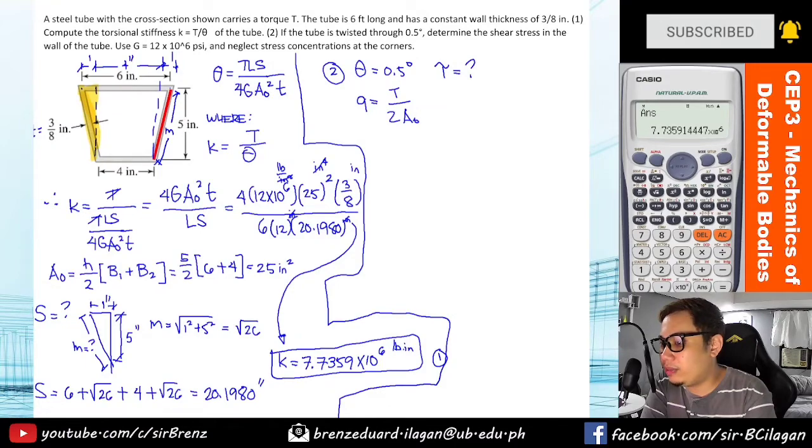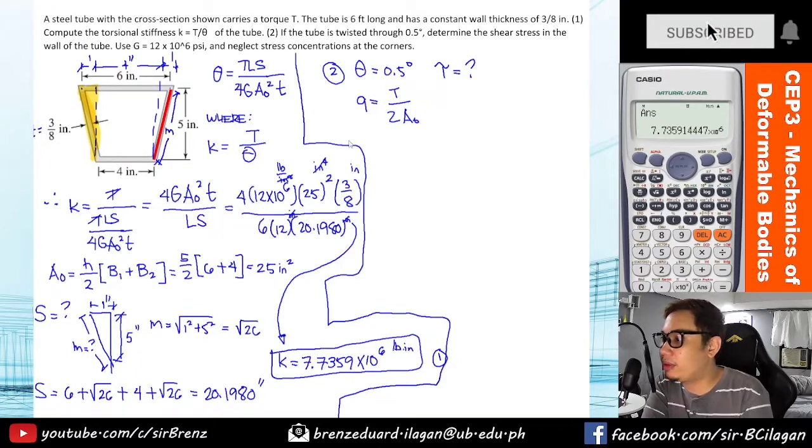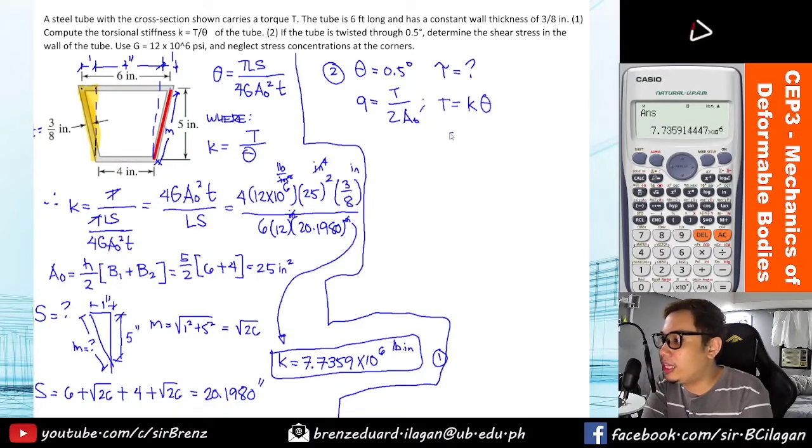Paano ba natin siya masosolve? So, we need to first determine the value of our torque considering na yung kanyang angle of twist is 0.5 degrees. So, paano natin mako-compute yun? Again, we all know that yung ating torsional stiffness na K is equals to T over theta. So, pwede natin siyang gamitin para makuha yung ating torque. So, torque is just equals to the product of your K, which is yung nakuha natin kanina, times yung theta. But then again, yung theta mo should be converted to radian first.